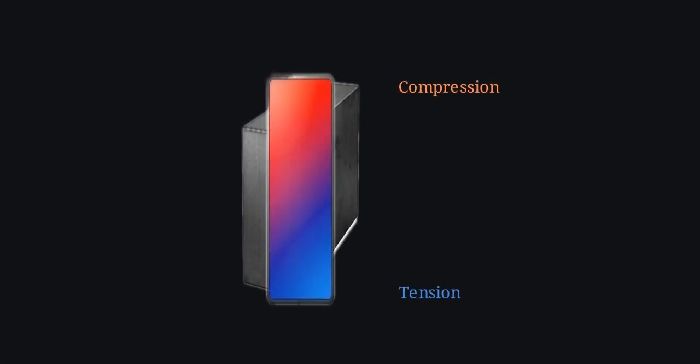When a solid beam bends, the internal forces are distributed unevenly. The material at the very top edge compresses, and the material at the bottom stretches. As you move toward the middle of the beam, those forces decrease linearly, leaving a neutral axis right across the center where the stress is exactly zero.